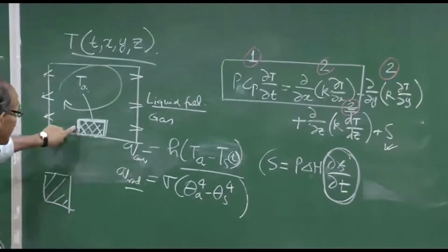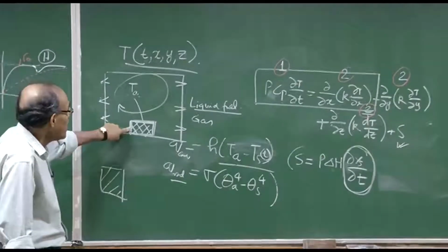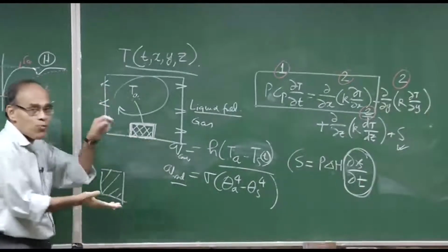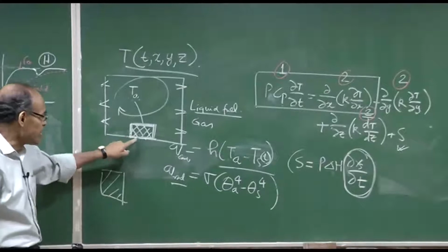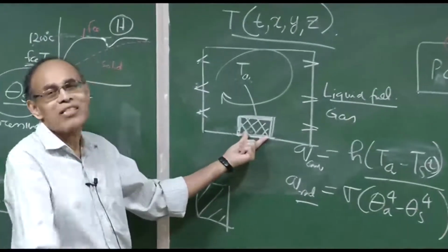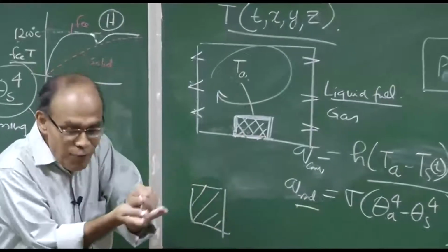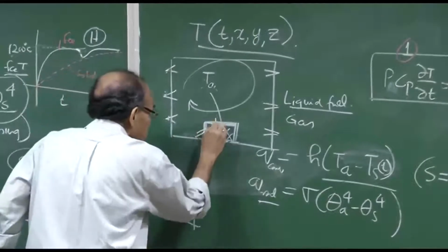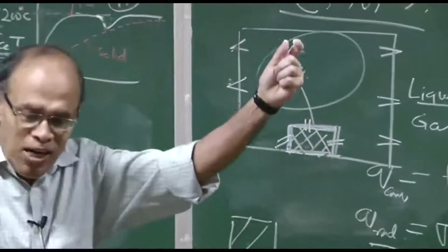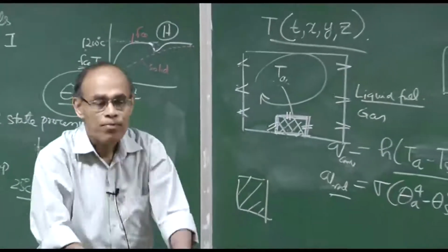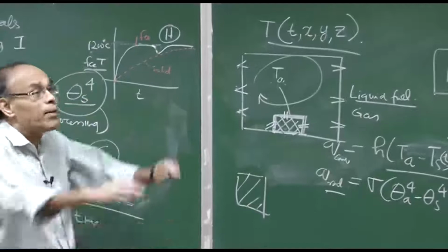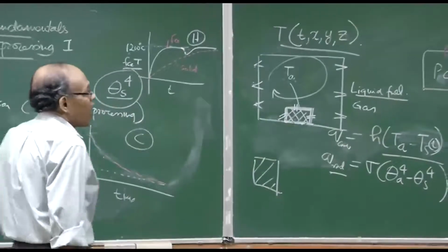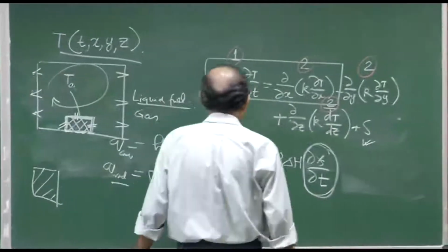What are the boundary conditions? As I have indicated, through surfaces, as you can see here, the ingot may be resting on the floor. So, the floor is exposed to a different kind of boundary condition. If it is resting on refractory, we can assume that there is not much heat exchange between the two, or if there is a refractory at high temperature, there could be a contact thermal resistance that could be taken. But if it is a 3-dimensional object, there are 6 surfaces; one surface is touching the bottom of the furnace, but the remaining 5 surfaces are exposed to the environment, and through the remaining 5 surfaces we will have boundary conditions.